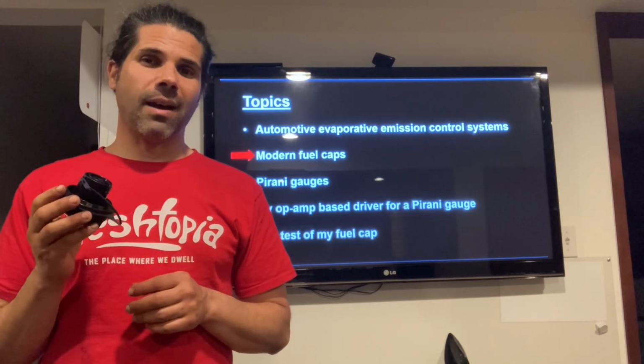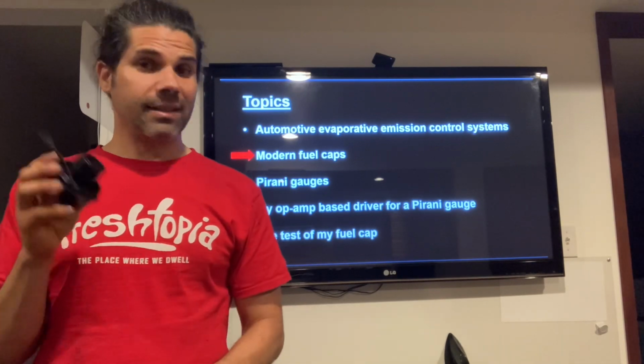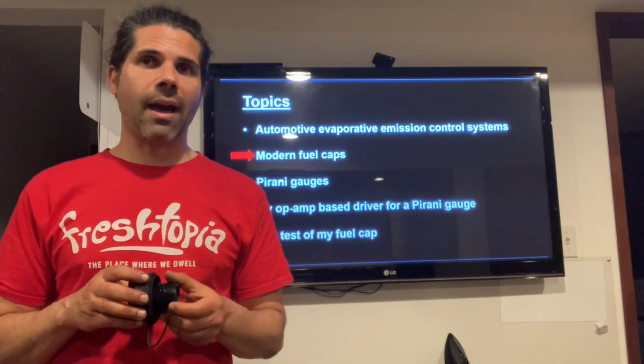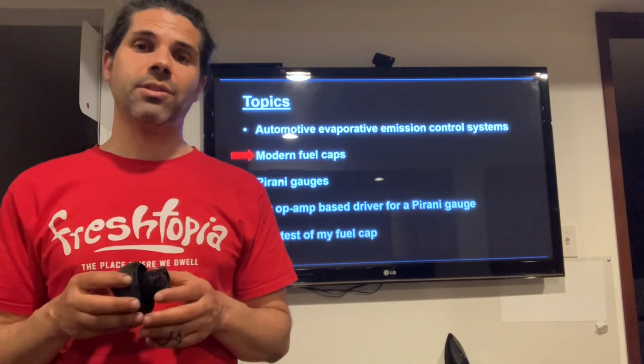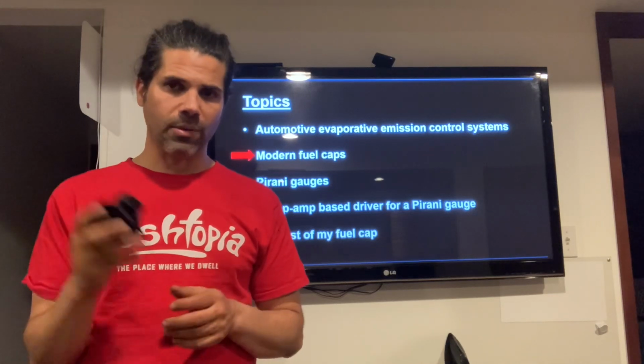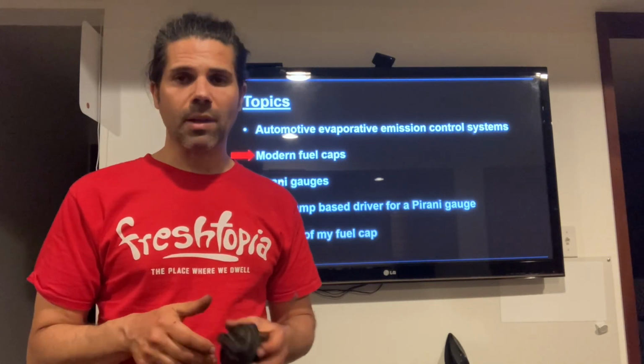So I suspect my fuel cap does not seal, that something is wrong. I don't really have it, process of elimination is what makes me think it's this way. So later on, I'm going to test this fuel cap for sealing, and we'll see how well it seals.